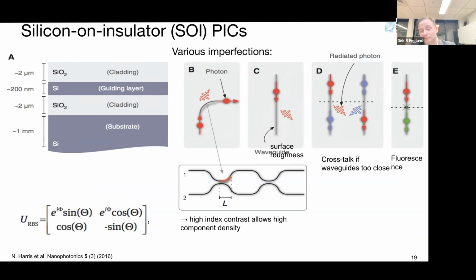If you bend the waveguide fast, then that solution does not work, because in the turn you can get multimodal behavior that can cause a deviation between the mode propagator that I've shared with you and the actual system. So generally people bend the waveguide gently to avoid any sort of higher order excitations.